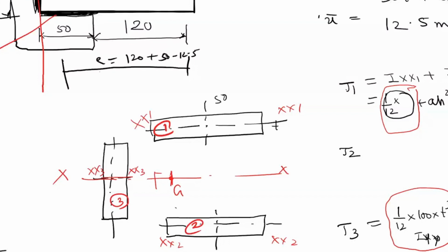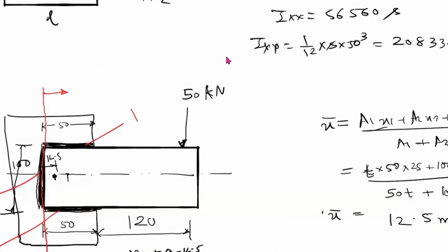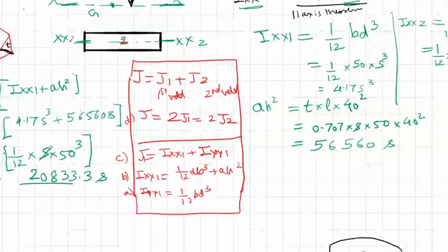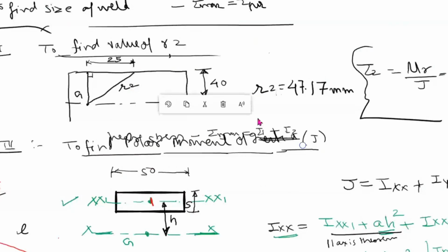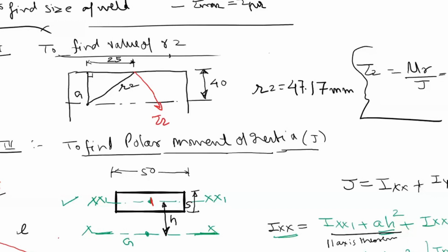And sir, I had taken cos theta equal to 50 minus x upon R2, sir, right? In the previous sum, yes sir, there the center was 25, so I had taken 25 upon R2 for cos theta. Let me check. Which is cos theta here? See, which is cos theta? Sir, base upon hypotenuse. Understand? This is tau 2. Okay, and tau 1 is vertical, correct? So this is cos theta because this is tau 2. Both are parallel. So this is theta.